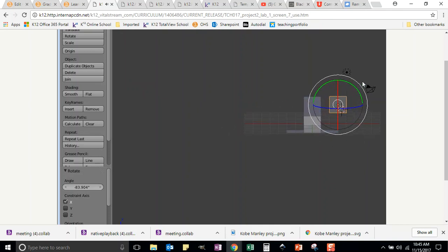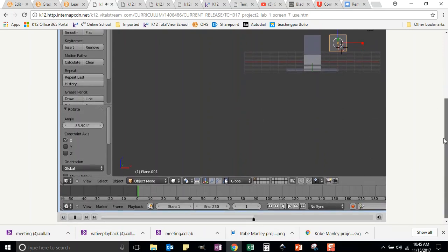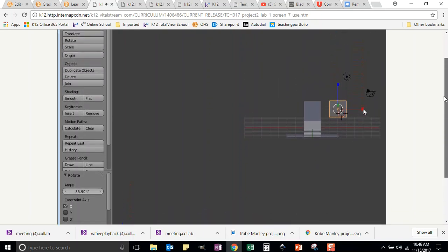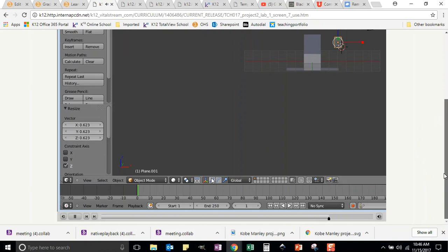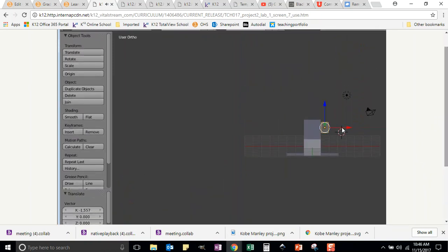Pan back to the front. Left-click the Scale Manipulator Mode button and use the square handles to shape the plane into a rectangle. Once the plane is a rectangle, scale the entire rectangle to fit on the front of the house. Left-click the Translate Manipulator Mode to move the rectangle plane to the bottom right of the front of the house. Move the plane along the X, Y, and Z axes.